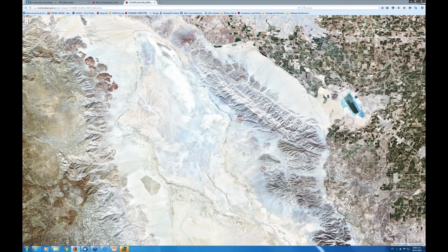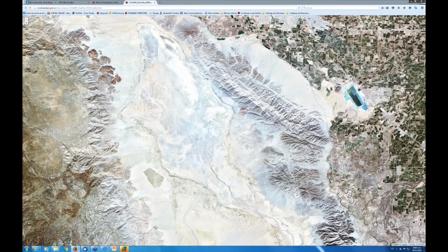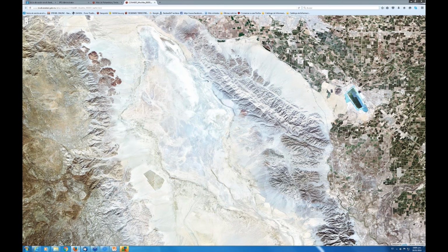You can see here that we already have a quite decent result from the GXL process. You also see that we still have some details here. Here, for example, you can still see the cut line. So in these cases, we have to do some manual post-processing in Geomatica. You define some so-called dodging points and decide, for example, in this case, I would like the right side to show more contrast.